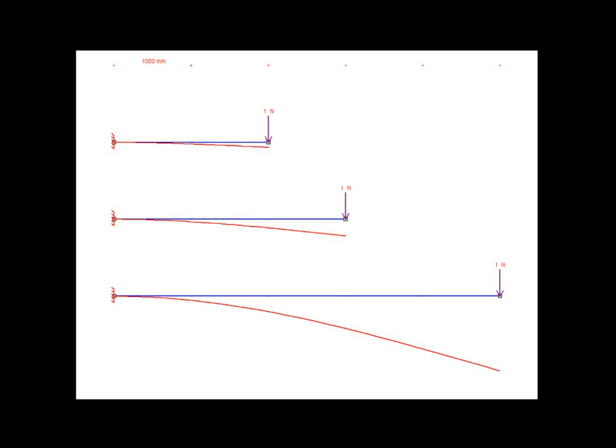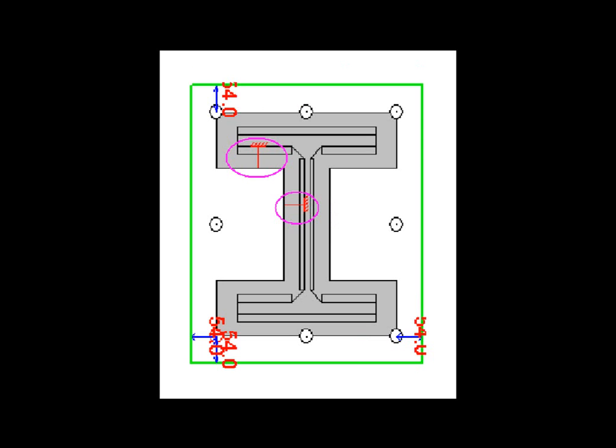In a cantilevered beam, the stiffness depends on the inverse of the cube of the beam's span. The shorter the beam, the greater its stiffness. The same consideration applies to the plate to which the bolts are connected. The cantilevered beam's span is comparable to the width to be added to the surface of the applied load footprint. This span depends directly on the thickness of the plate.